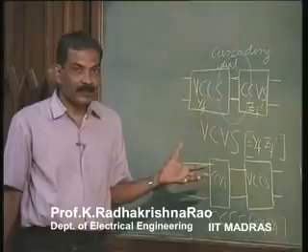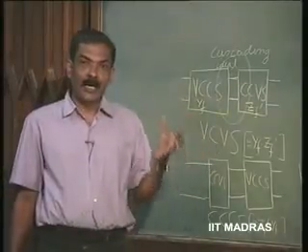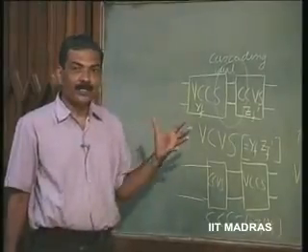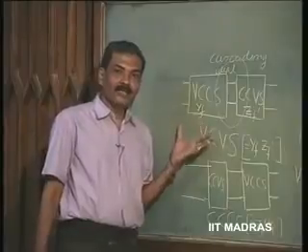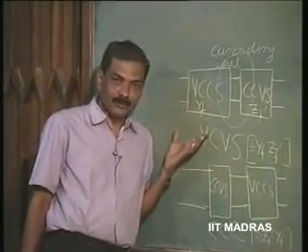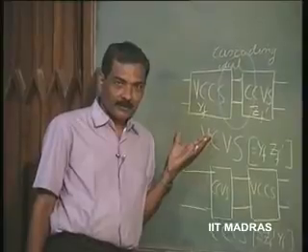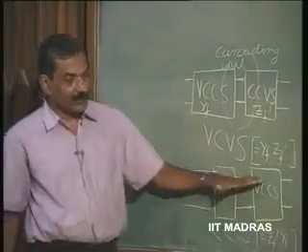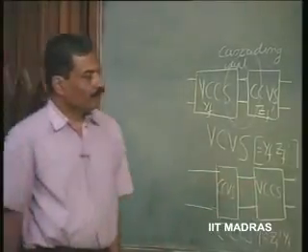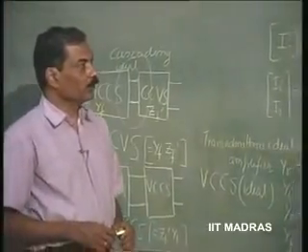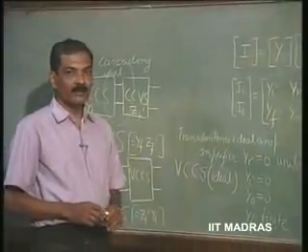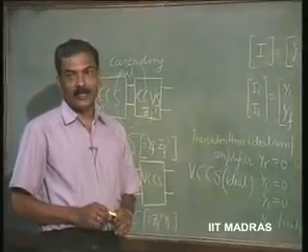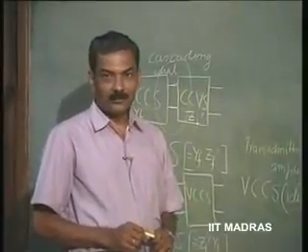So, it is necessary that these two must be studied, and possibility of designing these two optimally should be investigated, so as to not unnecessarily waste time on other two designs. Right. So, we have voltage control voltage source realized this way, current control current source realized this way, and therefore, we could say that these two ideal amplifiers are more basic than the other two, which will be again discussed in terms of now what are the parameters.